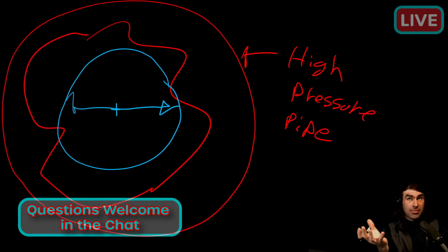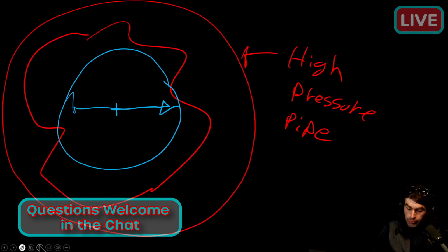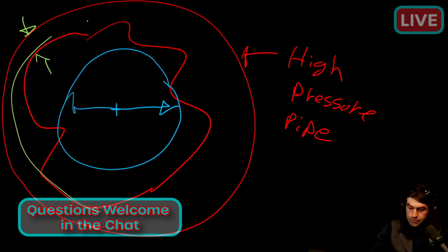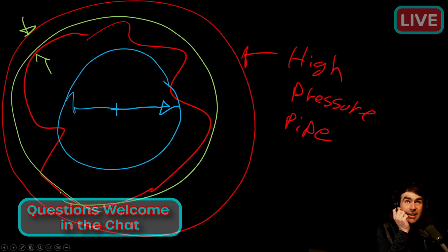What's the maximum? What's the least material condition of that hole? Because what we want to do is report back, do we have any potential issues here? In that case, you want your fitting algorithm to kind of draw outside the lines, if you will.